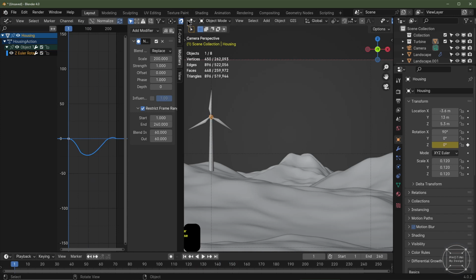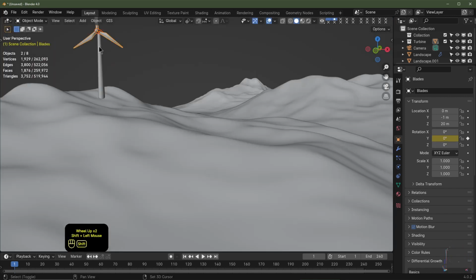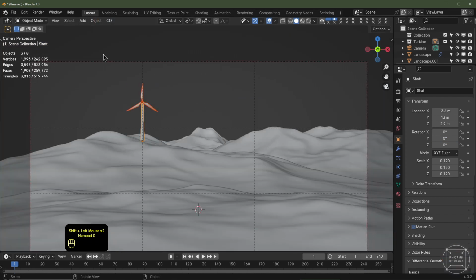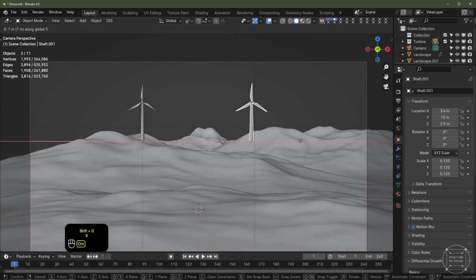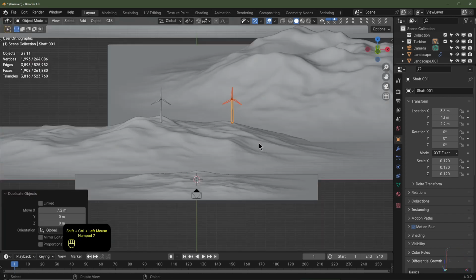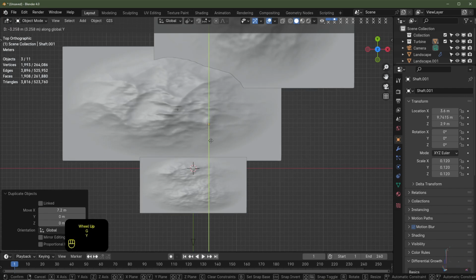Right, so now that that's in place, take my cursor to the top left here till we see the crosshair. I'm then going to left click, hold it down, and just drag it across, and we'll cancel that window out with all these objects selected here. I'm going to go into camera view. I'm going to hit Shift D and hit X to drag it on the X axis to around about there. I'm then going to go into top view. I'm just going to drag it on this landscape over here.